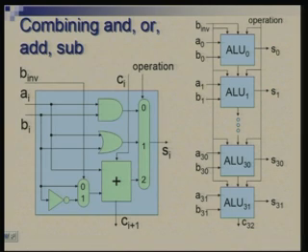Well, subtract has no subtract immediate, because if you add a negative constant, you can effectively do subtract immediate. So, effectively that means 7 instructions: AND, OR, add, subtract, and then AND immediate, OR immediate, which is ANDI, ORI, and add immediate. Okay, these 7 instructions will all utilize this part of the circuit.